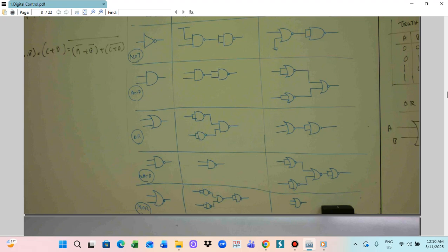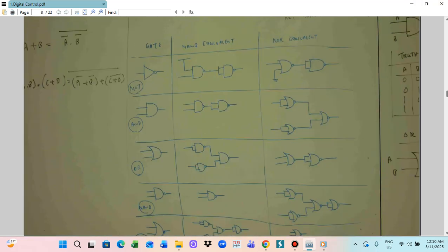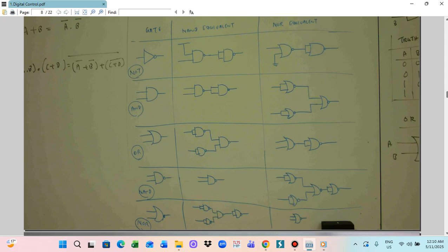If you can't get the IC, for example, you only have the 7400 IC. With the 7400 IC, you can only construct the NAND gate. NAND gates are what most ICs provide, so they are more widely available. But you can find the 7408 or 7432 to construct the AND and OR gates. It doesn't matter, you can still use the NAND gate and make connections like this, and you can get the other gates. This is why we use De Morgan's theorem.